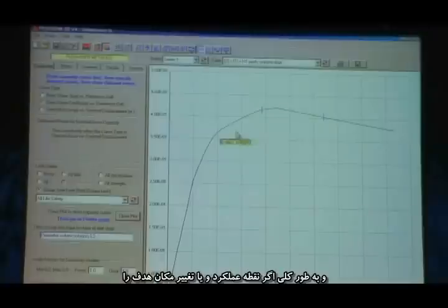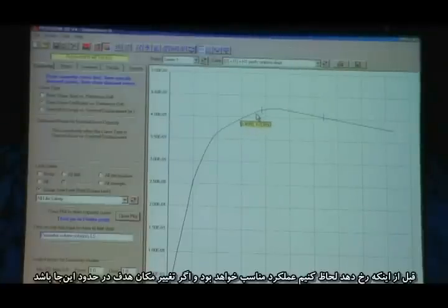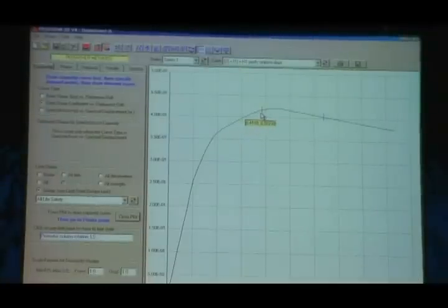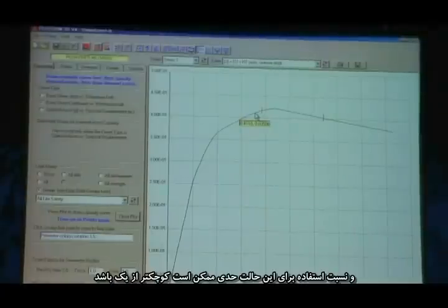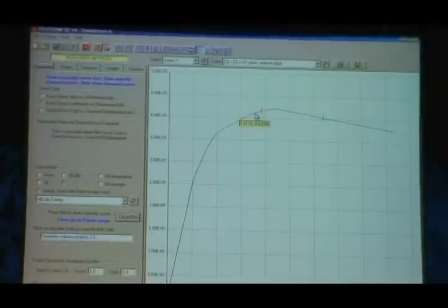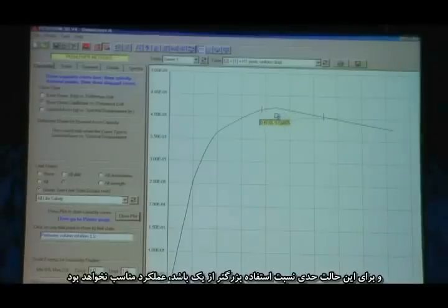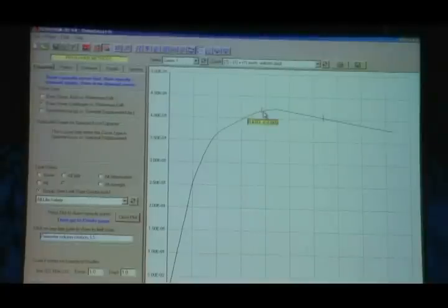And basically, if I get a performance point or target displacement which is before this occurs, then at the target displacement my usage ratios are all less than 1, the performance is okay. If the target displacement is out here, then the usage ratio for this limit state would be larger than 1, the performance is not okay.